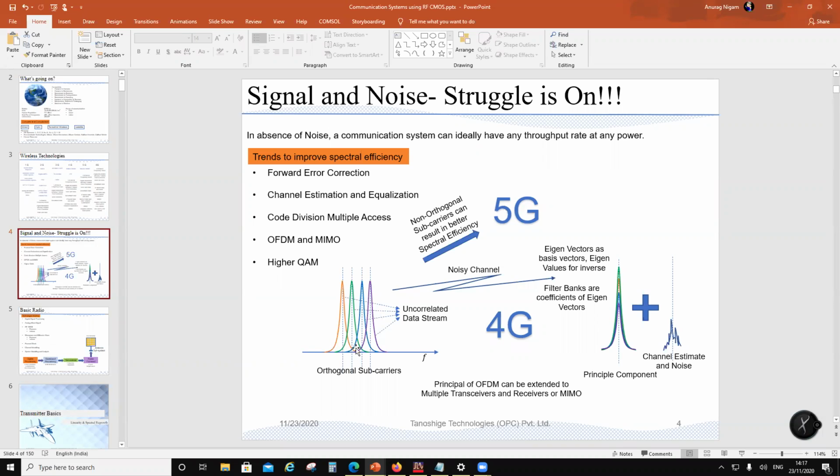Second thing is that your channels are orthogonal. So the subcarriers can be very close to each other, right? There can be overlap, but because the information is uncorrelated, it really doesn't matter if you spill out a lot in subcarrier channels. So these subcarriers can come much closer, and the channel interference is not much of an issue because data wise they are orthogonal. That's why the spectral efficiency goes up. You understand what I'm saying? It's because of the subcarriers.